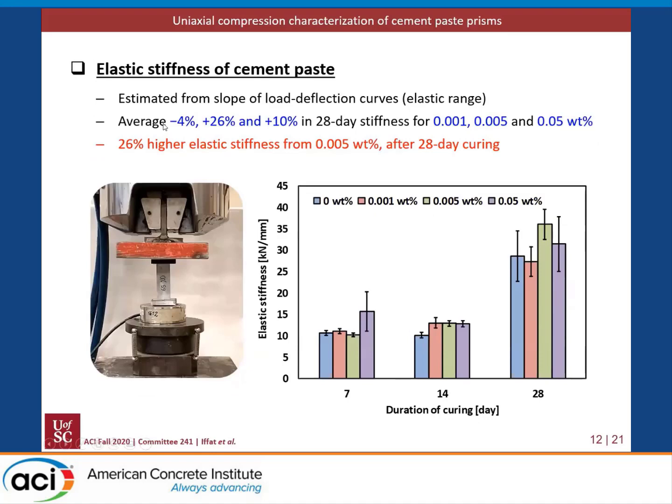We also obtained the elastic stiffness of the paste by obtaining the slope of the load deflection curve in the elastic range, and similarly 0.005% gave a higher elastic stiffness value compared to 0.05% after 28 days of curing.